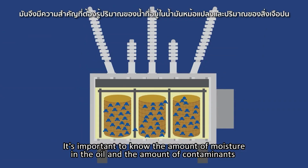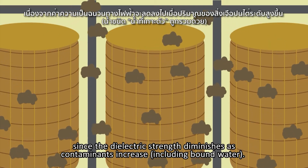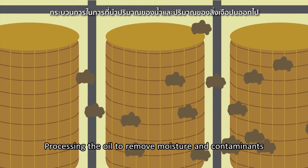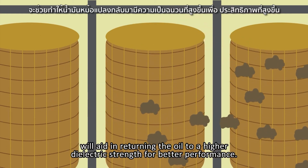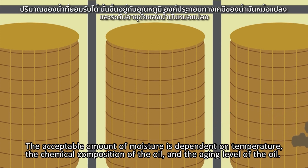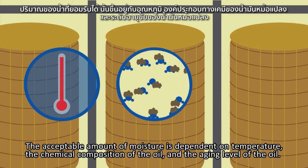It's important to know the amount of moisture in the oil and the amount of contaminants, since the dielectric strength diminishes as contaminants increase, including bound water. Processing the oil to remove moisture and contaminants will aid in returning the oil to a higher dielectric strength for better performance. The acceptable amount of moisture is dependent on temperature, the chemical composition of the oil, and the aging level of the oil.